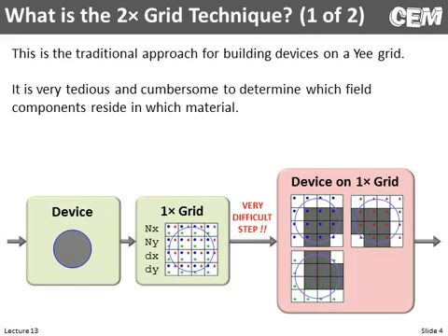When there's a curved boundary that ends up slicing through the middle of a Yee cell, that places some components outside the material and some inside. So at the boundaries they can differ a little bit, and somehow we have to figure out a way to coordinate all this in a way that's easy and manageable. Doing it the conventional way is not easy, and that's pretty difficult.